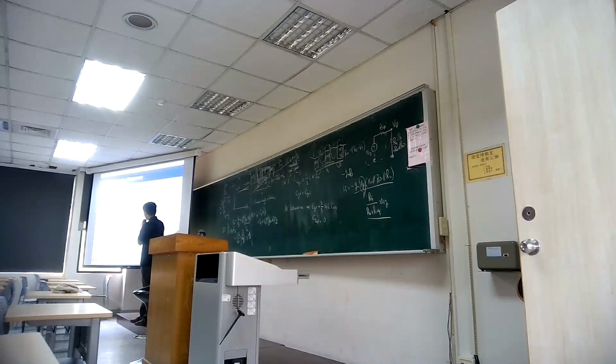But if you are working in the saturation regime, the CGS will be more significant, and we also get additional overlap capacitance. So what is overlap capacitance? We only consider capacitance here, but your metal connection at the source side is not precisely at the edge, right? So there will be an overlap in between. That is what we call the overlap here.